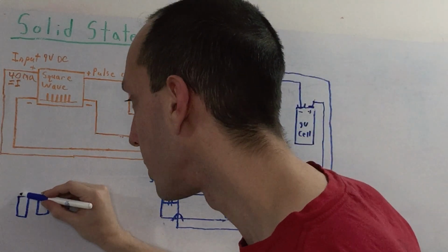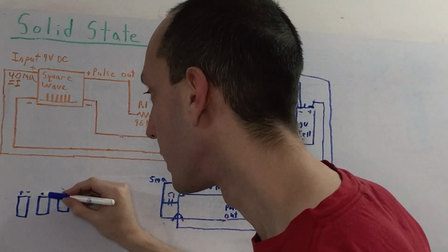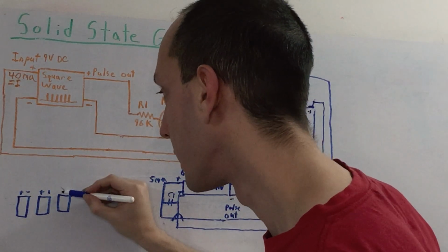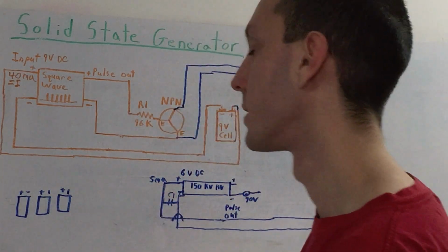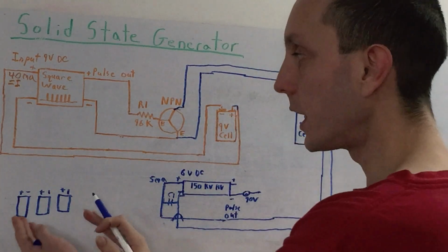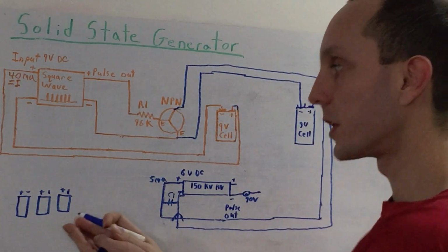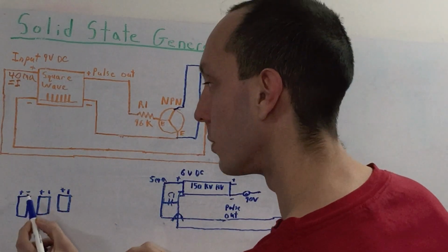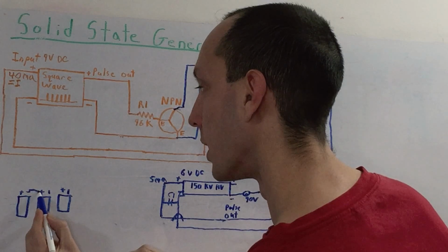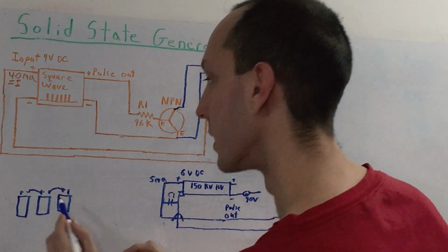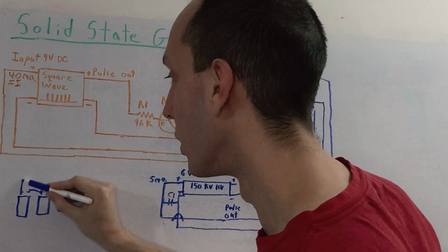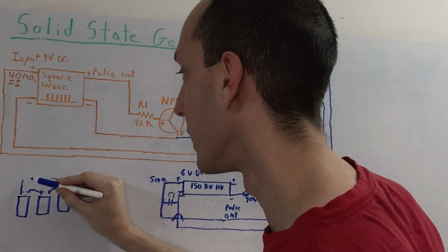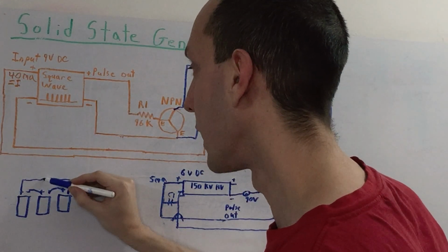So we're going to go plus, minus, plus, minus, plus, minus. So typically if we would want to run the series or parallel configuration, right? Which means that it would be pretty easy. Minus goes to plus, minus goes to plus, and then we connect our load here, like this, and our light bulb